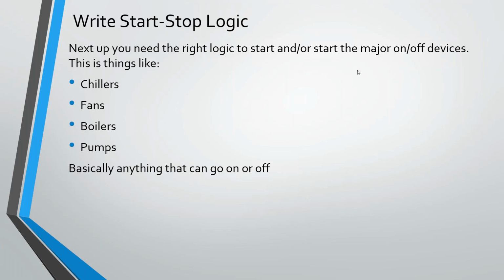So I like to start off by just turning things on, because honestly, quite often, whether we're doing a chiller, whether we're doing an air handler, we have some linchpin on-off state that determines whether that program's going to work. For an air handler, it may be opening an outside air damper. For a chiller, it may be enabling the isolation valves. We need to figure those out and get those written.